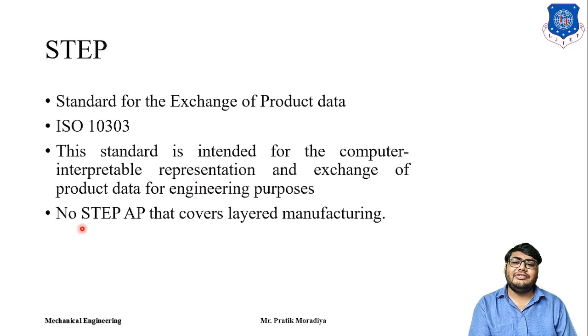But the problem is that there is no STEP application protocol that covers layered manufacturing. STEP has many application protocols which are used for different applications such as FEA, computer aided manufacturing, CFD, etc. But there is no STEP application protocol that is used by layered manufacturing. So one has to develop this application protocol to use the STEP file directly in additive manufacturing.